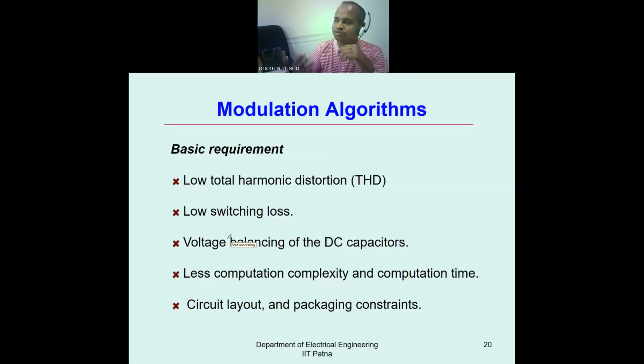So when the sampling was not proper because of these many things, we decided that the sampling time must be fixed, and all the packets must be the same length, same size, same byte, or whatever you call it in the digital domain. So we thought it should be very small and cut that way. They started comparing a sawtooth wave with a reference wave, and according to that frequency they switched on. That technique is called pulse width modulation.